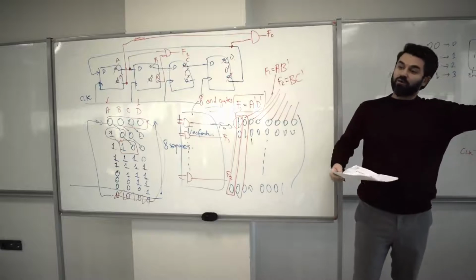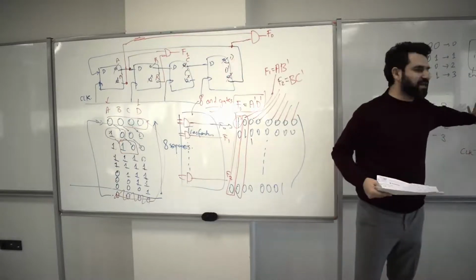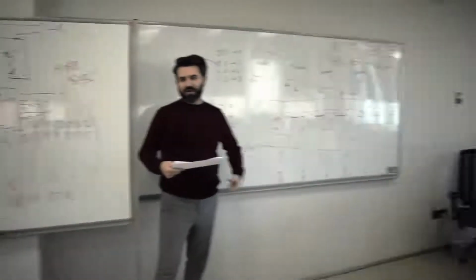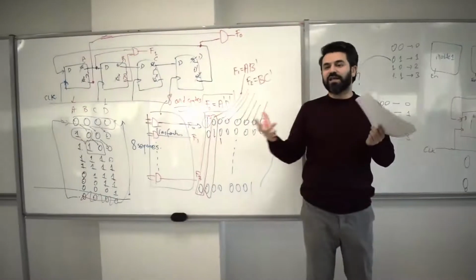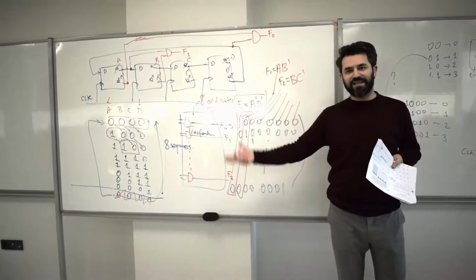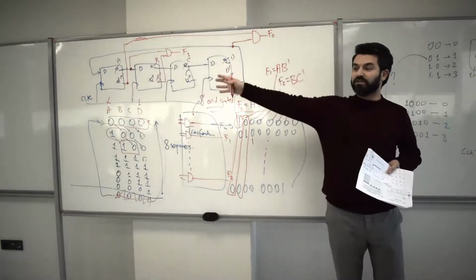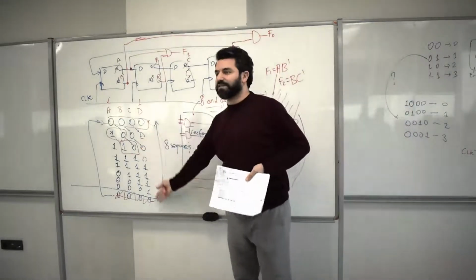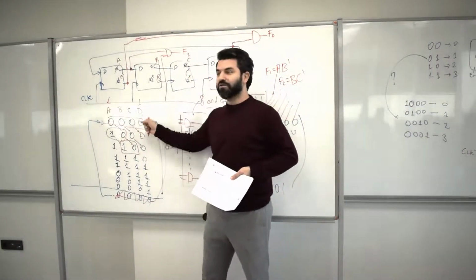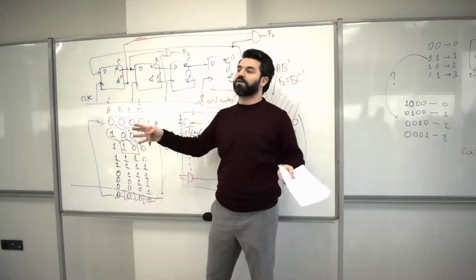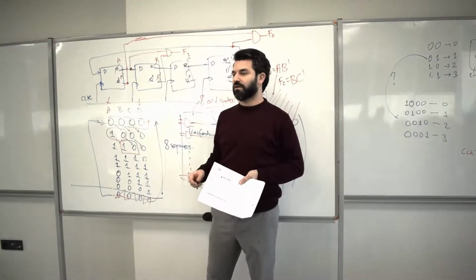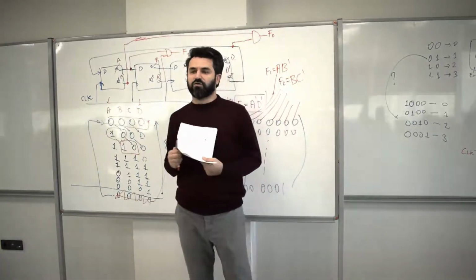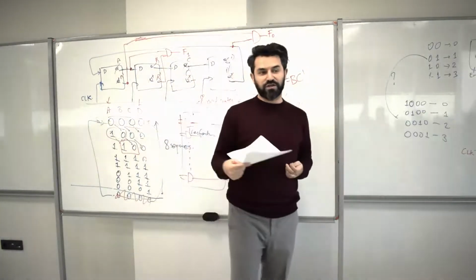Right? That's the most other extreme. The ring counter is on one extreme. You don't use any combinational circuits to generate a counter that is in this format. How about the Johnson is just like in the middle because it generates 8 states, 8 sequences. But maybe on the other extreme, you can have a counter that can generate all possibilities. In other words, it starts from 0, 0, 0, 0 up until 1, 1, 1, 1, but all possible binary combinations. Would that be a counter? I mean, do we have such a counter? Right? That might be another interesting question.